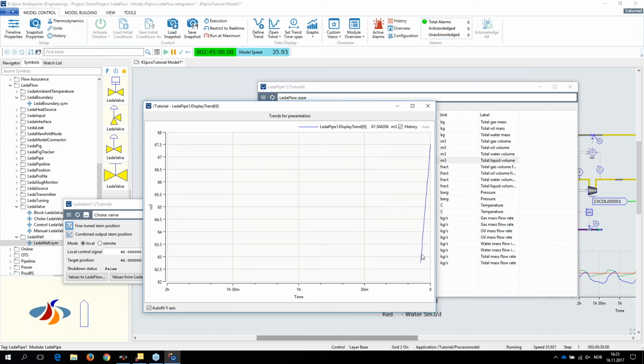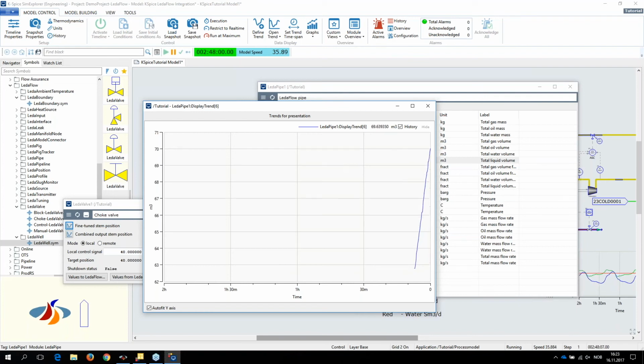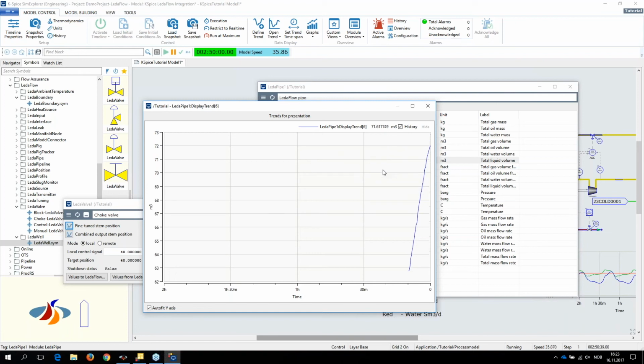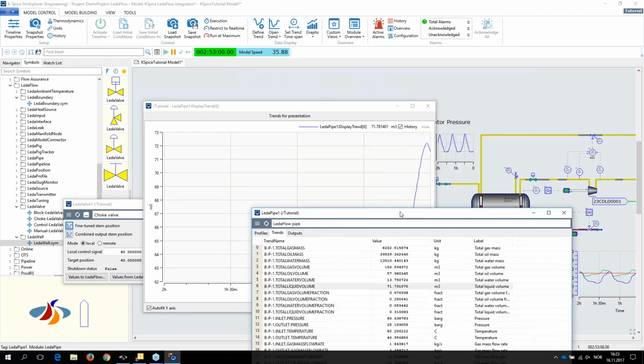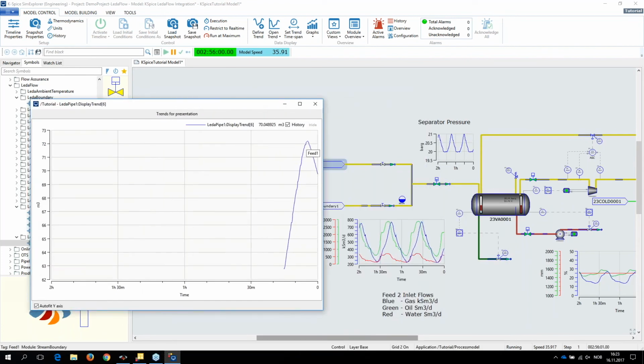And we can see here that we have an increasing liquid amount in the flow line and riser before there's a plug happening, and it forces and purges the riser. You can see that this corresponds to the slug pattern.